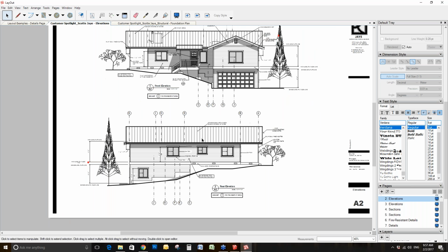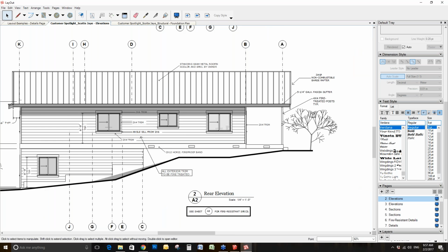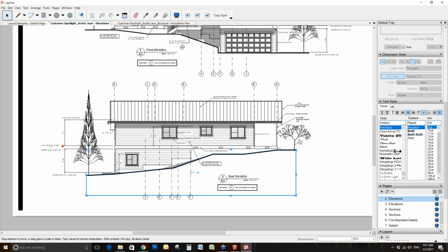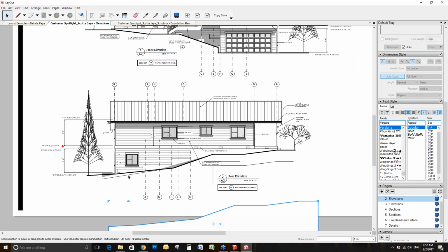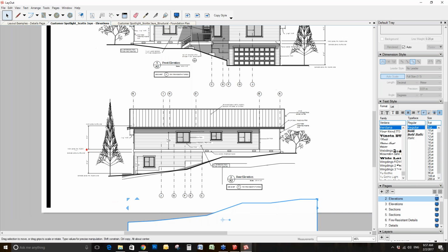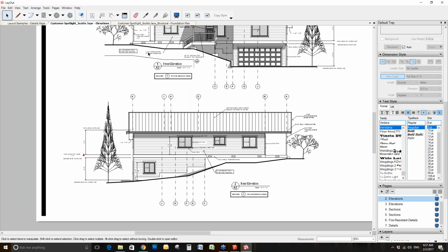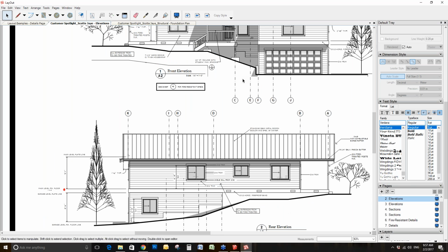Elevations, same thing. How do you set up elevations? You set them up with a masking layer. The masking layer is very important because in your Plusspec and your SketchUp model, you're seeing through. You haven't set up an actual solid part that is going to read as your site. So it gives you the ability to hide the parts of the model that you don't want shown.